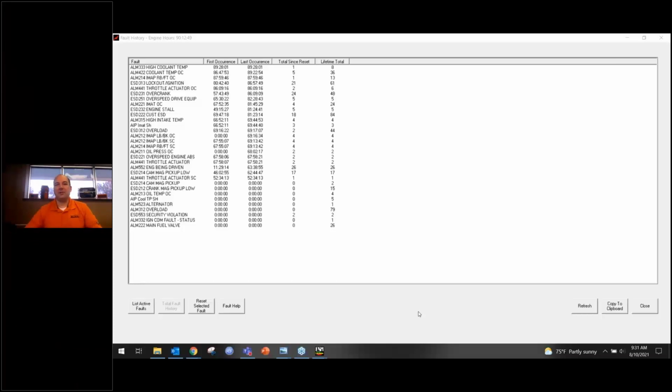So here we have a scenario of something that was very simple, a coolant temperature sensor that was saying, I've got a problem. Not understanding how to follow through the troubleshooting tree, or what would have caused that to run to that high coolant temperature, led them down a bad path. They figured, hey, if I just keep disconnecting sensors, I can keep the engine running. But then they ended up with a much more costly repair, and then figured out all they had to do was open up that valve.